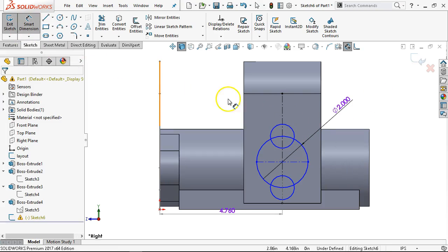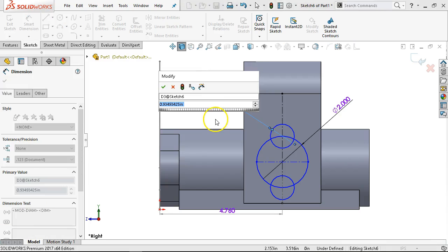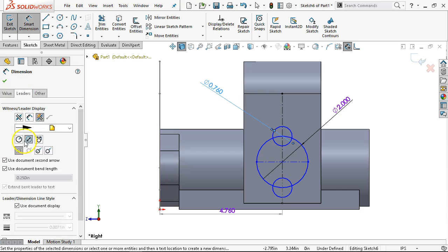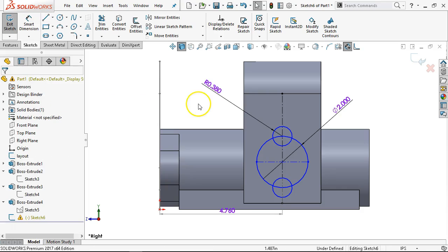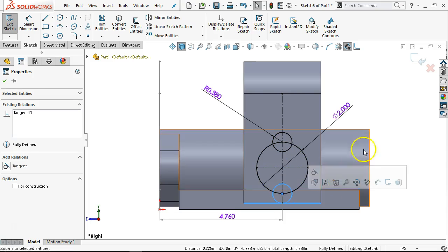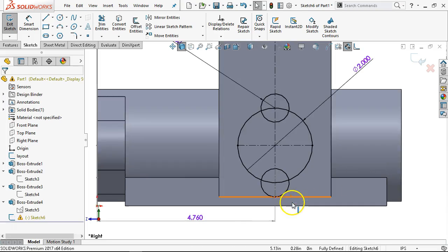All right, so those were equal. All right, so we're in a diameter. This was a radial dimension, so radius of 0.38. So if I go to the 0.76, we'll change back to the radial. And if those are done correctly, then that face will be tangent.